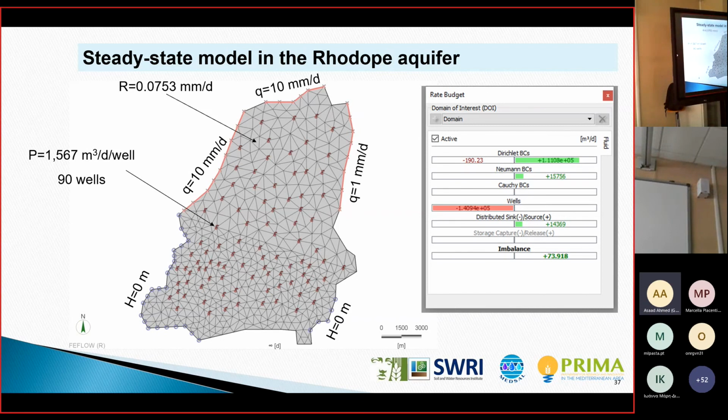Oh, yes. Obviously, when I say the difference should be the minimum, you should measure this with some statistical criteria, like mean square error. For this particular case, we didn't use an auto calibration. I have used it for other models, not for a groundwater model but for a surface water model. It is an option that you can use only one of the statistical criteria, or you can use both of them. It depends on the type of the problem.